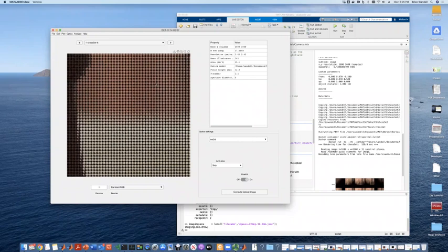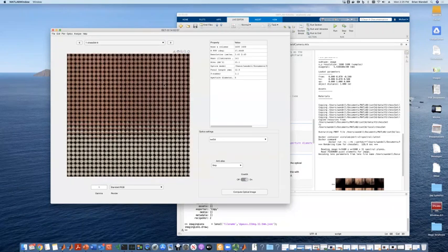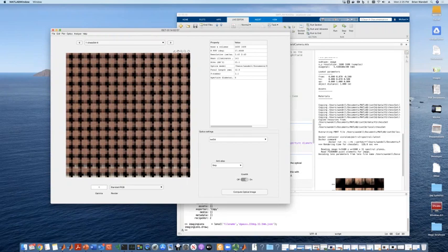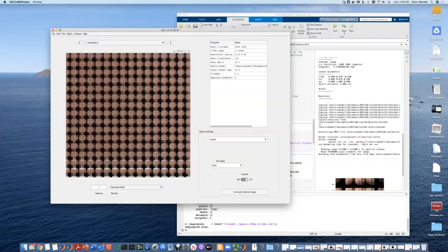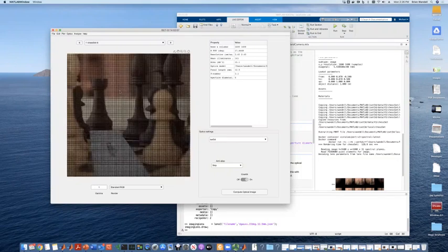In each one of these little circles, that's the irradiance. This is a description of the irradiance that's about to fall on the sensor underneath. The reason there are all these little circles here is because that's underneath a particular microlens. So one microlens, the next microlens, the next microlens, and so forth. And so there's 320 microlenses in each dimension. Each one has 5 pixels. So if you look at how many rows and columns a sensor has, it's 5 times 320. So that's going to be 1,600 pixels that we need for the sensor. And this is under one microlens, under the next microlens, and so forth. And each one of these is a spectral irradiance. And that's the whole image that we're simulating right there.